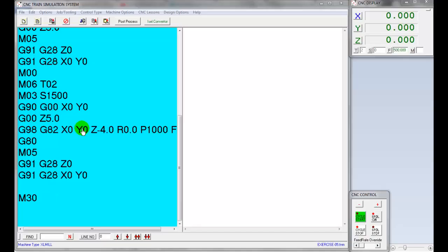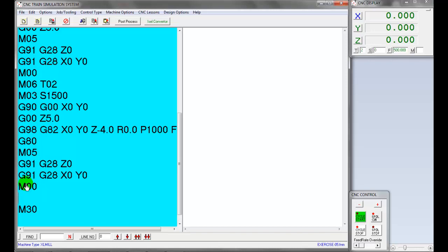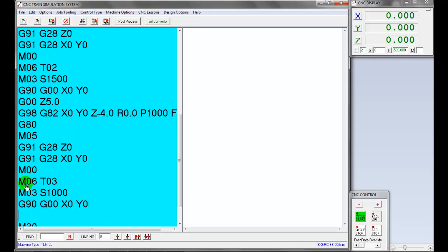Let's continue the part program after the 5 mm drilling and countersinking operations. M00 is program stop or pause to verify the holes are machined correctly, also to remove any burrs. Change the tool to the M6 tapping tool by the M06 command. The tool number is 3, turn on the spindle by M03. And RPM is 1000. Position the tapping tool in rapid traverse X0 and Y0 first, then move the tool down to 5 mm above the top surface of the workpiece.